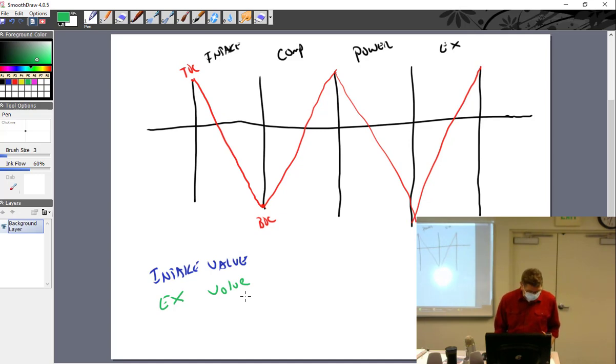And according to this drawing, I just said that the intake valve opens 50 degrees before the piston reaches top dead center. So it opens 50 degrees, so it's opening over here. We'll just put a little 50 degrees. That's when it opens. I didn't need that line down the middle. Don't know what I was thinking there, but there it is. So far, we know that the intake valve opens. Well, why is it opening up so early? And what stroke is it actually opening up into?